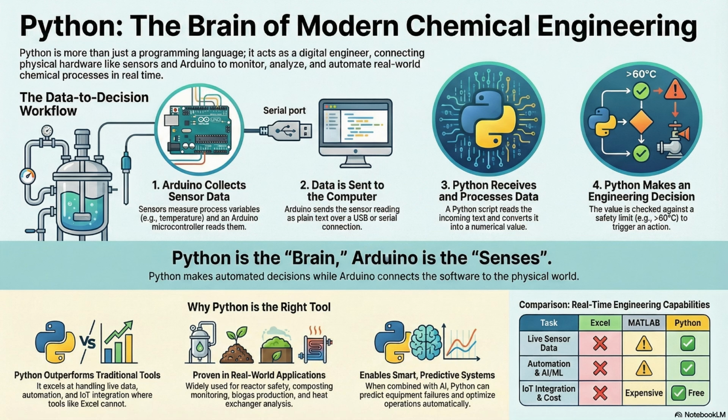So we go through a very specific four-step process in Python. Step one is just establishing the link. The handshake. The handshake, yeah. Use a function called serial. And you have to be meticulous here. Your port name, like COM3 on Windows, and your speed, the baud rate, which is usually 9600. They have to match perfectly. Perfectly. If they don't, you're just yelling into the void and nothing will happen. Okay, connection established. Now Python is listening.